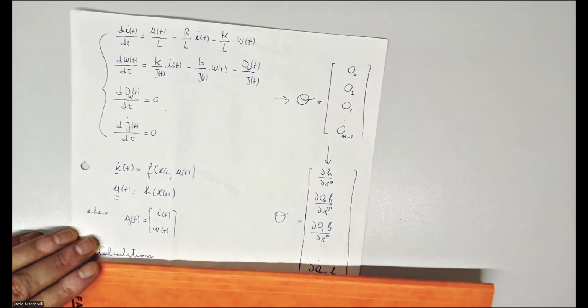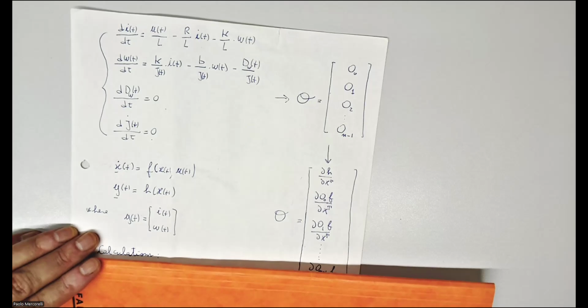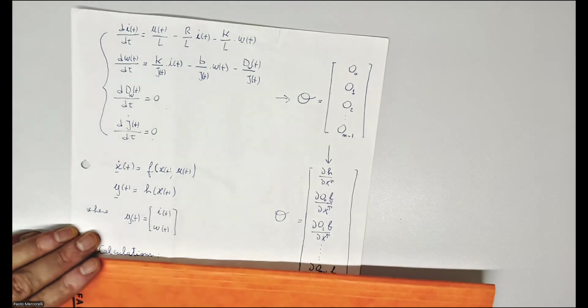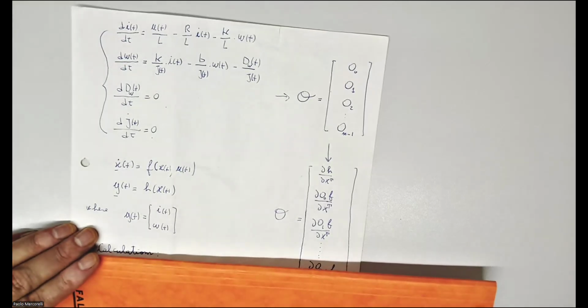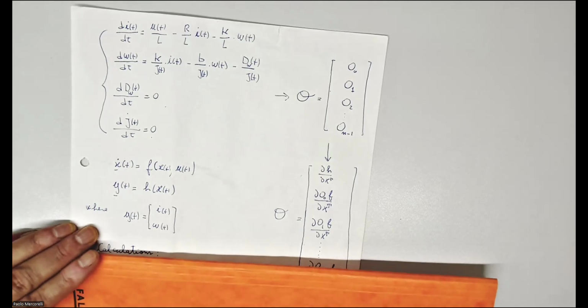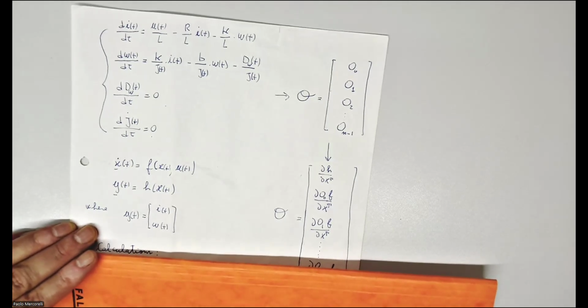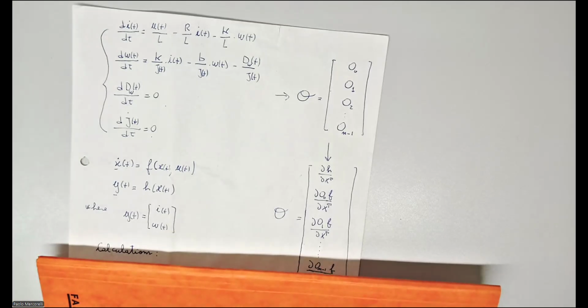The estimation, if the hypotheses of Kalman are guaranteed, is better than the measurements. Intuitively, to understand that this is a filter, we filter the noise. Of course, in order to say that it is better, it must be optimal, because not necessarily a filtered signal is better than the measured one. You can also destroy the information if the filter is too strong.